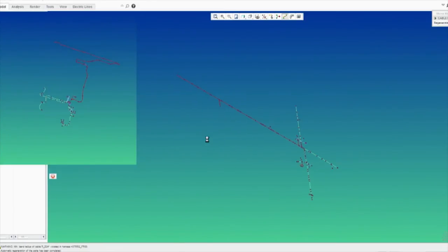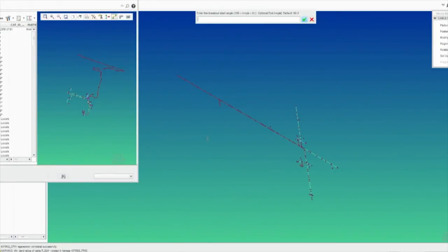So the harness has been flattened using the auto fan process as we do, but some of the ideas we also generated, that we do at Caterpillar, is we change every dimension and move breakout segments and so forth to 90-degree bends and a small bend angle, so that we don't get the sweeping curves. Our suppliers like the sharp bends, and so if I go into a full flattening mode, it's regenerating the model now, and it's doing some spatial recognition to make sure that our breakouts go into the right side of the segments. It's still regenerating here just in a moment.